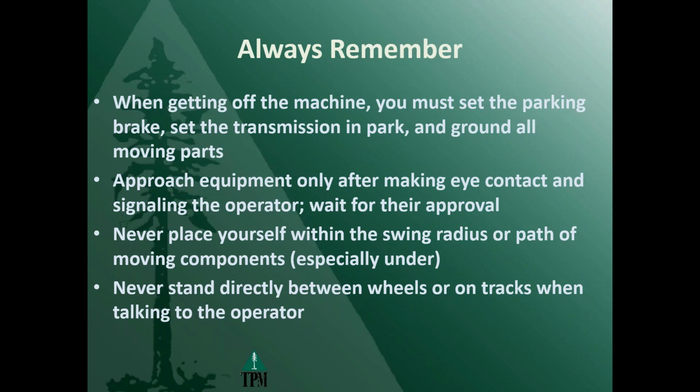We've got to teach our folks to make eye contact and get communication with the operator, even if it's just waving at them, until they acknowledge we're there or we get their approval to approach the machine. And don't stand directly behind the wheels or the tracks while you're talking to the operator, because their foot can slip off a pedal. They can be trying to set the parking brake, their foot comes off, and they roll over somebody. Just be real careful. Once again, we've got to teach our folks on the ground too, to not get in the swing radius or the path of these pieces of equipment.